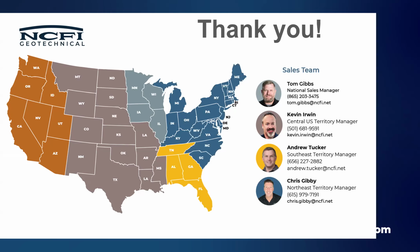I'm not sure whether I'm answering your question or not, but it can be used in expansive soils without issues. We realize that it's always going to be a problem. We're not completely filling in when we're dealing with expansive soils. For instance, if we're injecting on a grid, we may leave some space for that to expand around it.